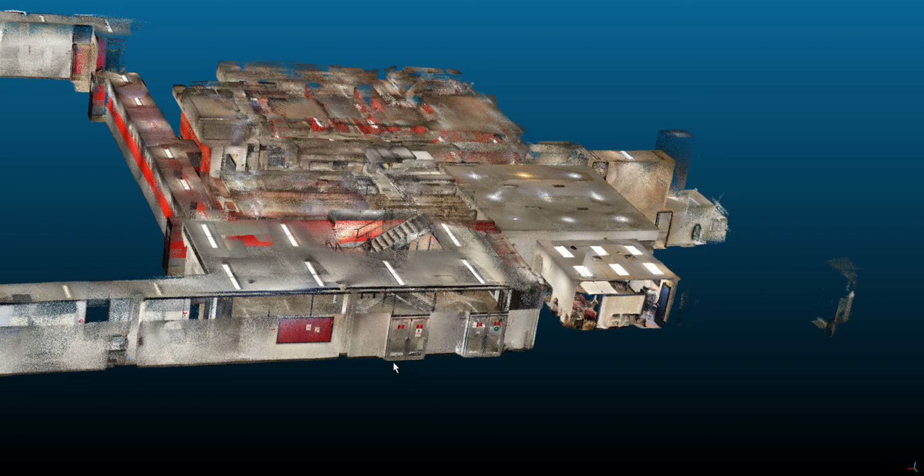What we did was we took 200 million points, which is the maximum recommended number of points to work with on CloudCompare such that your system doesn't start to crash. And we divided that number by the number of scans that we had, which was roughly 200. It came out to be about 1 million points per scan. Given that each scan is roughly the same amount of points, it ended up working out okay to use this method. So each cloud is 1 million points after subsampling it down.